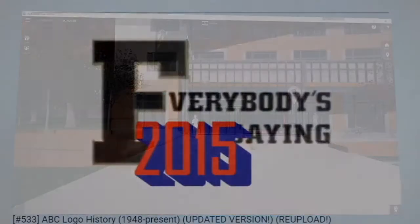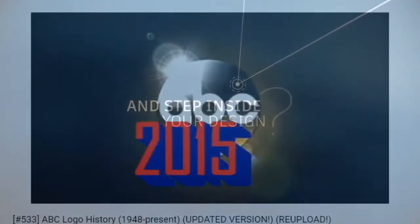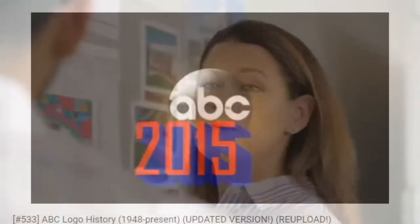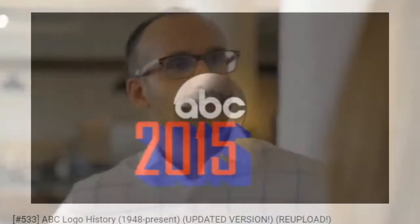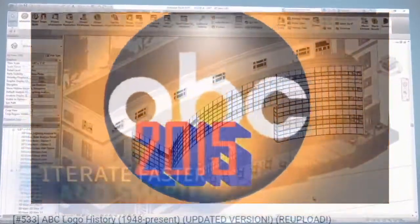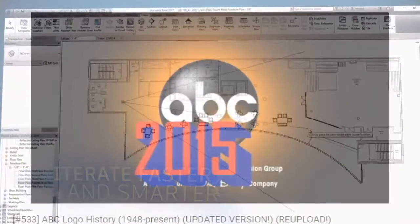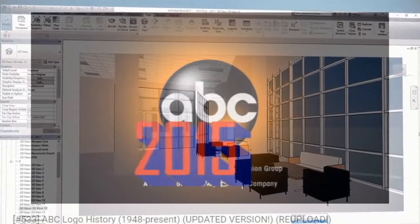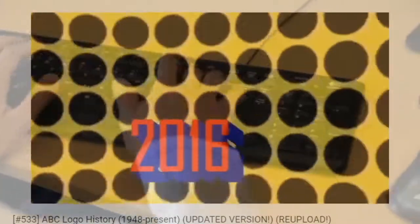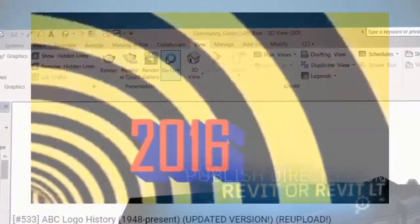Okay, now, that being said, creating a custom floor edge, you can apply a great deal of flexibility to a floor assembly in early design. As we described previously, you can create a floor for early design phases that accommodates the floor, structure, plenum, and ceiling in a single floor type. You can also apply a customized edge to this type of assembly for more creative soffit conditions as at exterior walls.